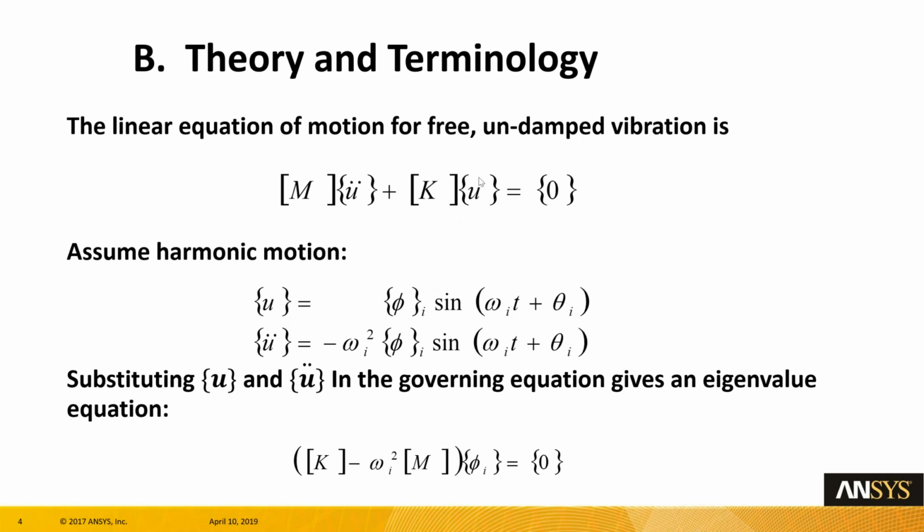So we are assuming that the displacements are a function of sine omega t, and you take a double derivative of this, then you get minus omega square sine omega t, and then you're left with this equation over here, which brings up that famous equation: f is equal to the square root of k divided by m. So that is the source of this.